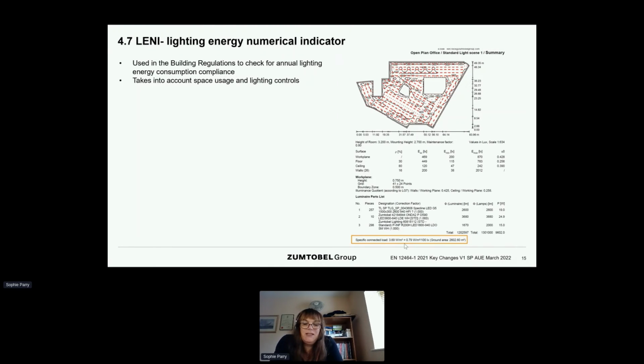Okay, and people say that's it, and they get transfixed with that number, and somebody might say this job has to be 5 watts per square meter or less, but that number is slightly misleading, because that's the worst case electrical load. That's everything switched on at 100% output, and it may be Dali lighting, for instance, it may be dim during operation, not using as much power. So that's your worst case. Useful for calculating your lighting circuits and getting your cable sizes and your volt drops correct, and your circuit breaker specified correctly. But that's about as far as it goes.